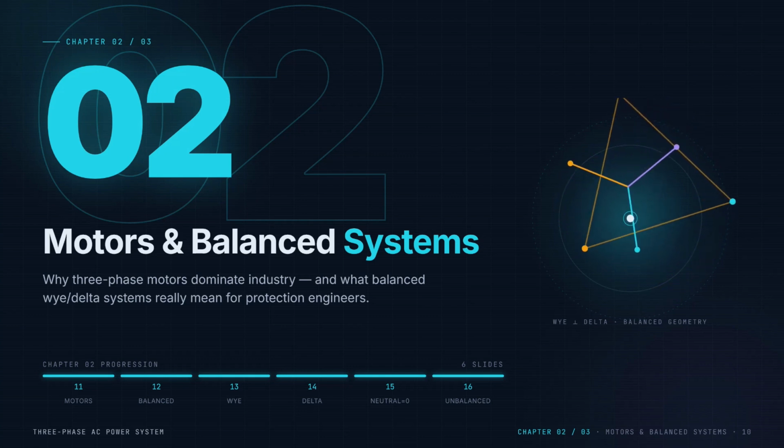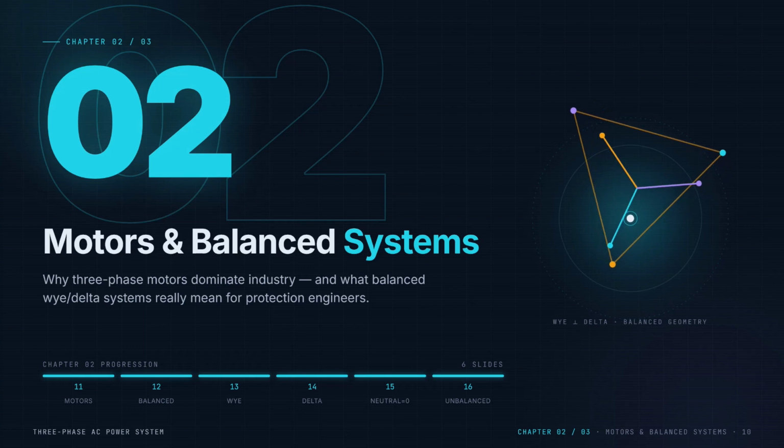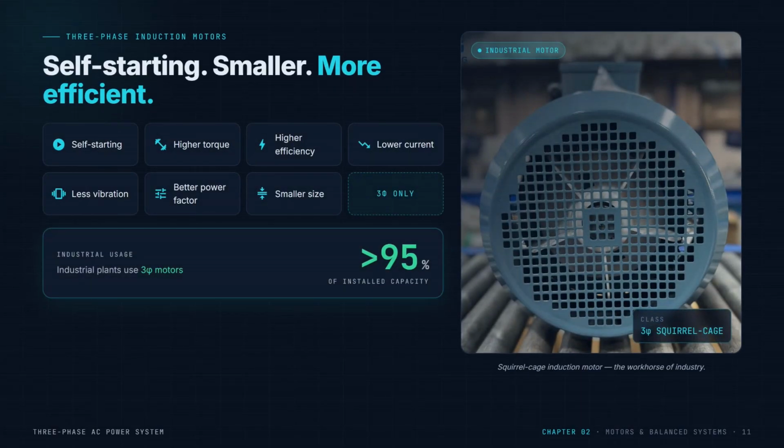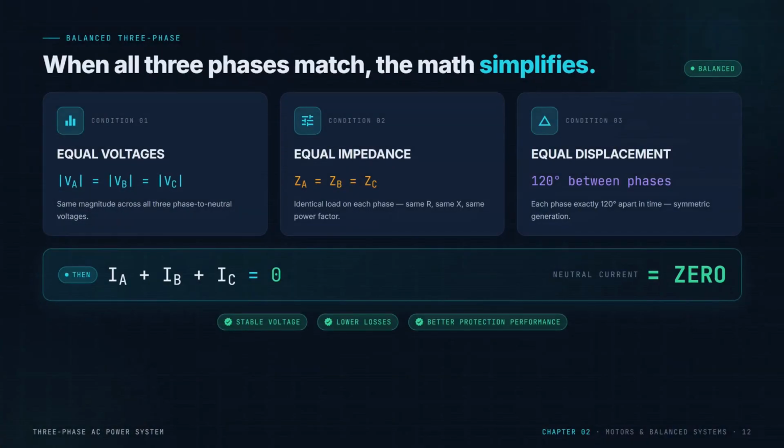Instead of using one stator winding, engineers place three identical windings inside the generator, each physically separated by 120 electrical degrees. As the rotor turns, each winding generates the same sinusoidal voltage but reaches its maximum value at a different instant. These three voltages are known as Phase A, Phase B, and Phase C. Because they are equally spaced in time, the combined electrical output is remarkably smooth and balanced.